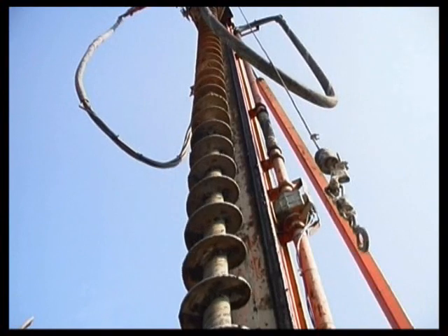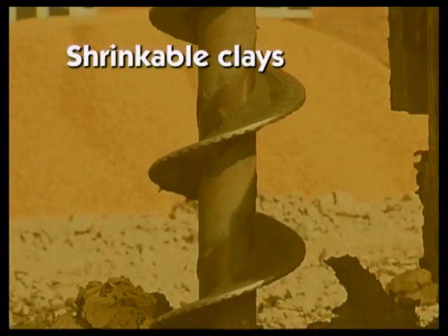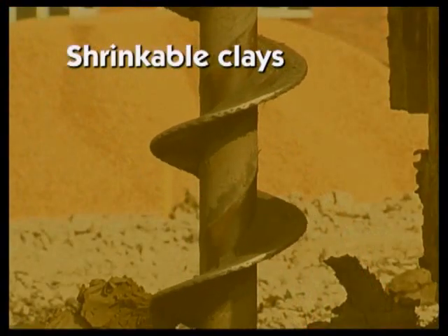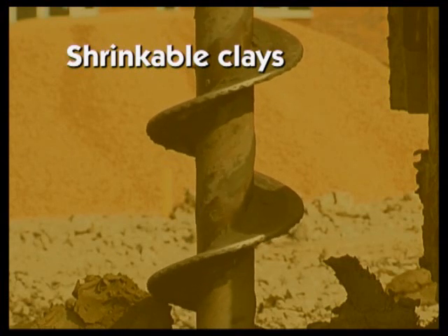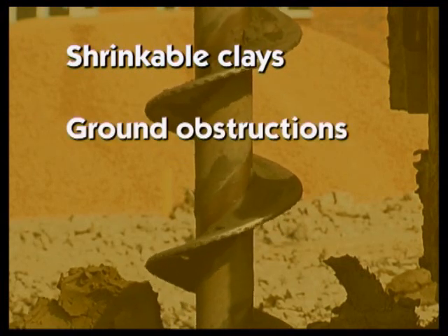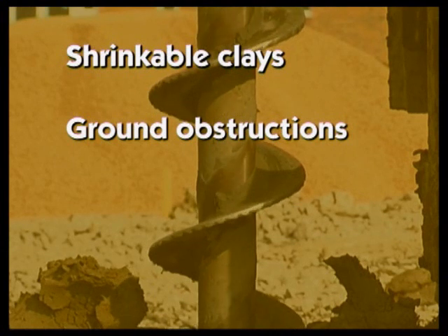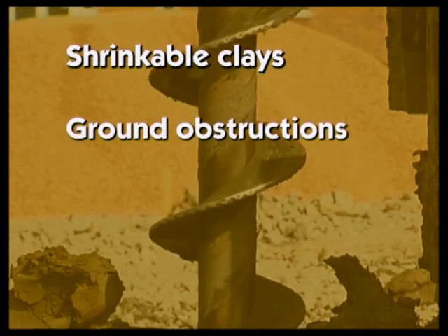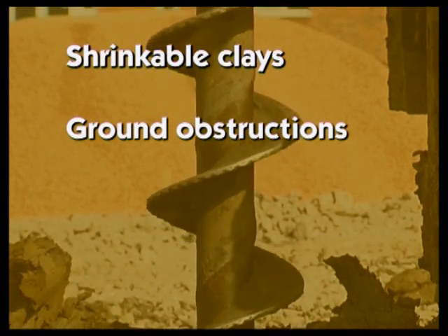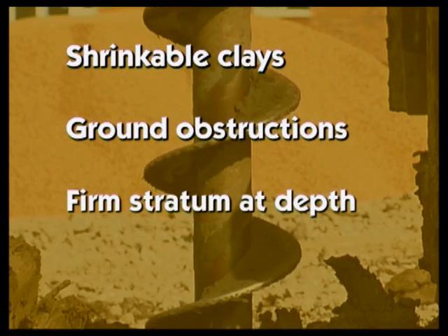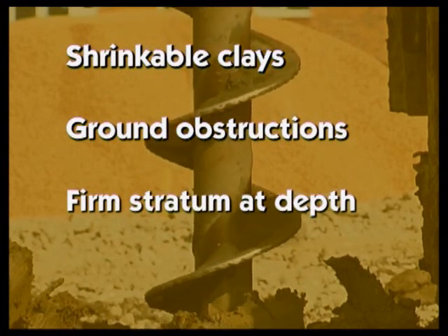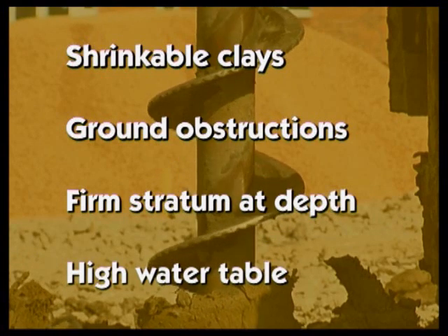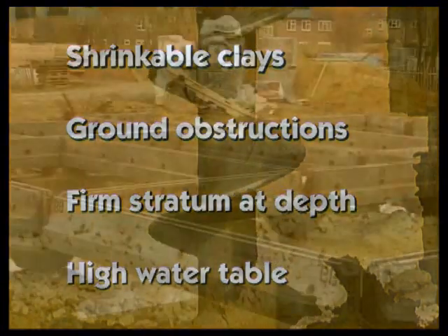Piles can be used on shrinkable clays where existing or felled trees are close to the foundation, where minor obstructions in the ground make trenching difficult, where a firm stratum is at too great a depth for strip foundations, and where a high water table will make trenching impractical.